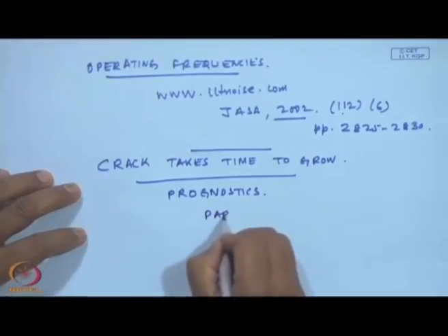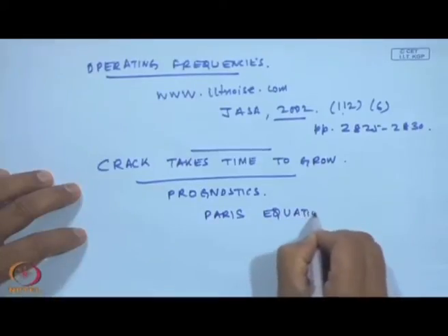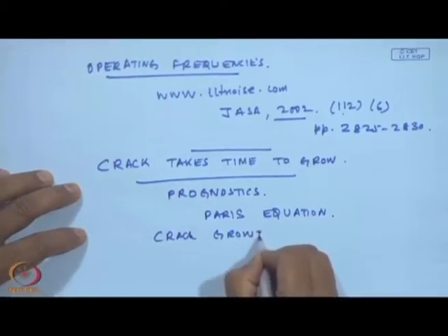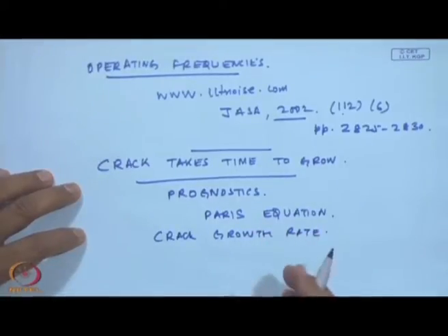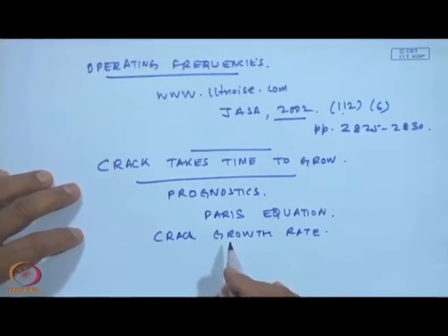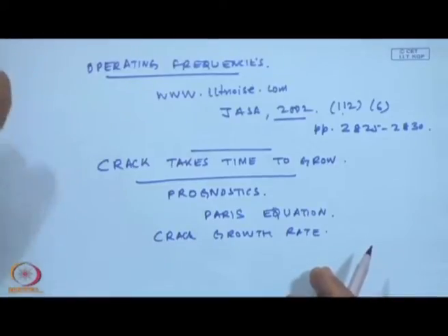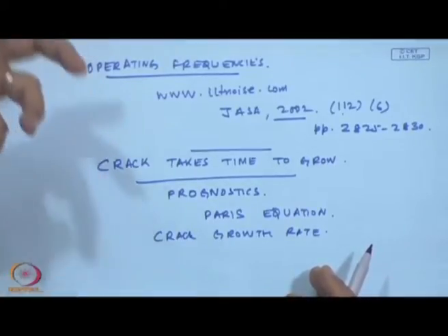Okay, you have the famous Paris equation for the crack growth rate, that depends on the material property, the crack dimensions, etc. So, it takes time to grow, and eventually the crack will grow to such an extent that the material would have become weak and it would fail. But through a mobility measurement, initially when the crack has occurred and it has just grown to a few A's, 0.5, where A I define as the crack depth by D, the crack has increased, we will see that the mobility value suddenly shoots up. So, mobility is sensitive to crack, other than just monitoring the velocity of vibration. By velocity of vibration, it would be very difficult for us to monitor whether a crack has occurred, but by doing the mobility measurements, we can surely say the crack has occurred.